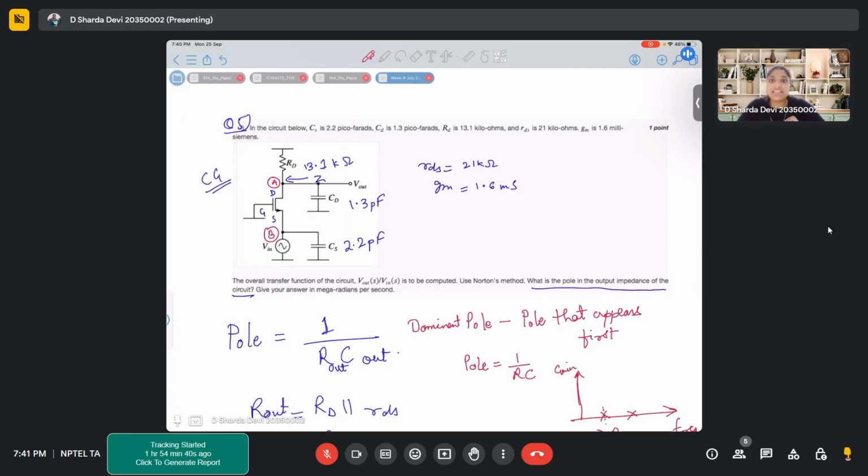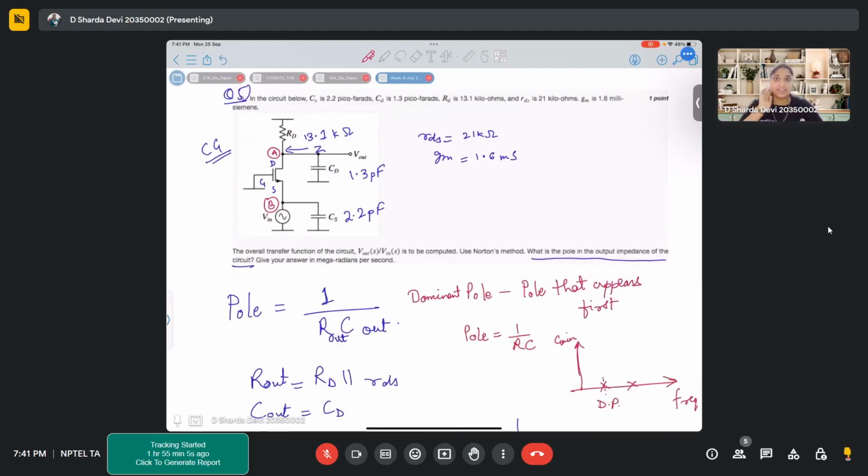So junction capacitance is between, let's say, your source and substrate, your drain and substrate. Whereas gate capacitance appears between your gate and substrate, and overlap capacitance appears between your gate and the source and drain. But it is not between two materials where a junction is formed. So that's how these two capacitors are different.